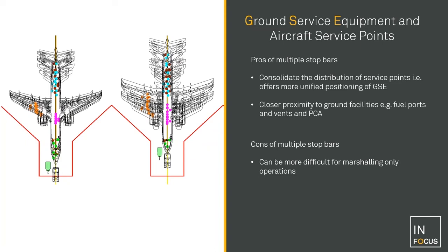For example, here, wing location, which has, of course, its advantages when you have fixed service ports or fixed service pits for refueling or preconditioned air. You'll see though that the 400 hertz, the green buttons at the front, are a little bit more further distributed, but not so extreme as what can happen to the rear of the aircraft because of the length of different aircraft.